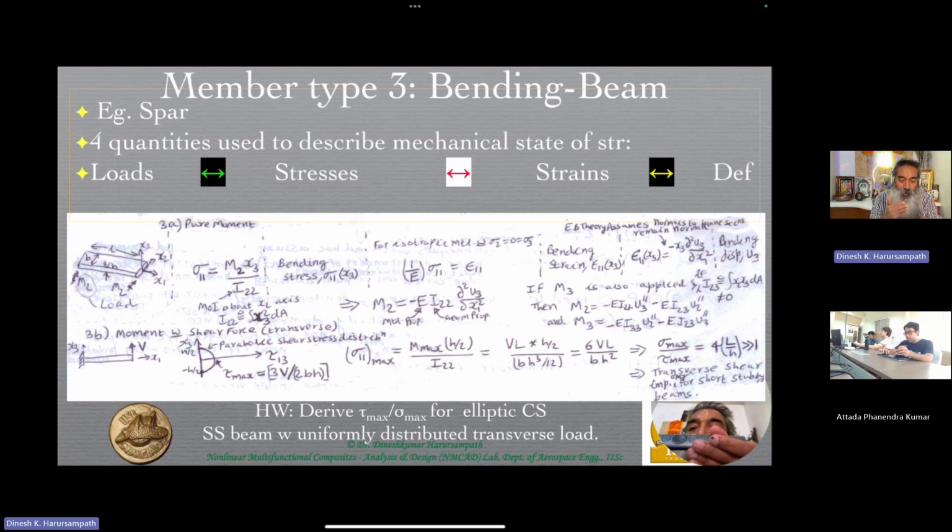How is that possible? Because the total integration of the tension stresses over the area on which they act and the compression stresses over the area on which they act cancel each other out, and therefore there's no net axial force in a problem like this. The only reason those axial stresses are present in opposite directions is to create a moment which counteracts the moment created by the applied load.